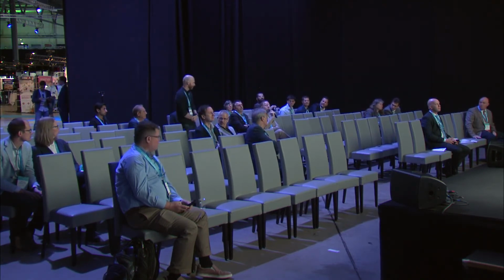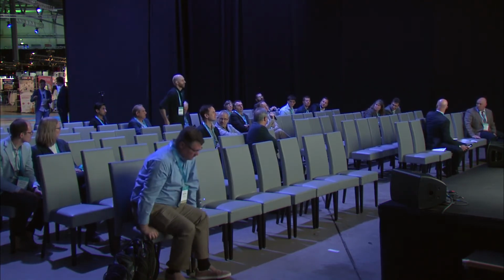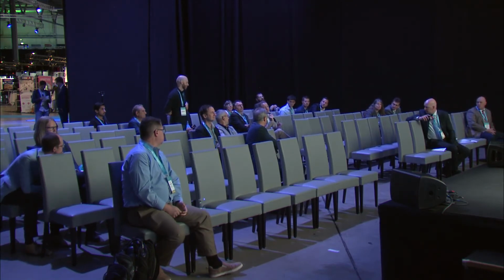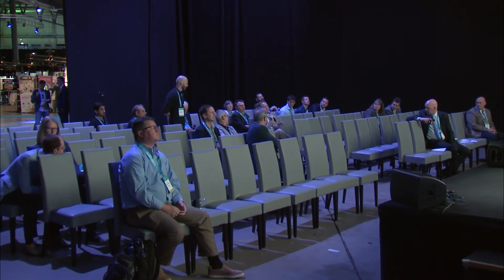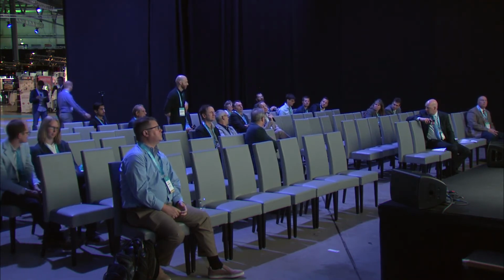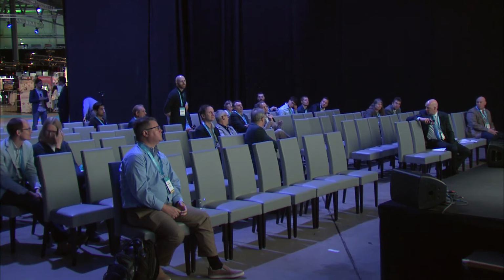Yes, good morning. So from your testing, can you see that there's any feedback regarding the current safety factors that we're using for structural silicone design? Because currently it is about 6 according to the ETAG, and some suppliers tend to push it down to like 4 for certain projects. What's your feeling on this one, having done all of the testing on the artificial aging?